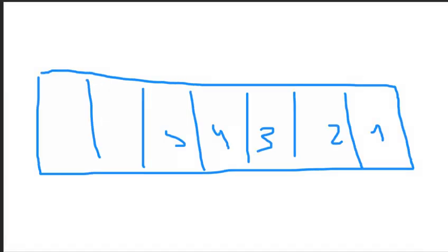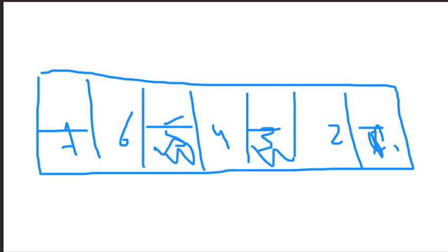I think we made that exercise even last week. This one. 1, 2, 3, 4, 5, 6, 7. It has a certain cargo distribution in the uneven tanks. It's alternately loaded. And I ask you to calculate the shear forces and the bending moments at every intersection of the tank.